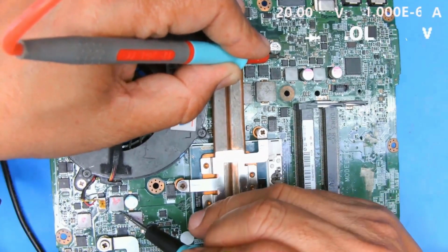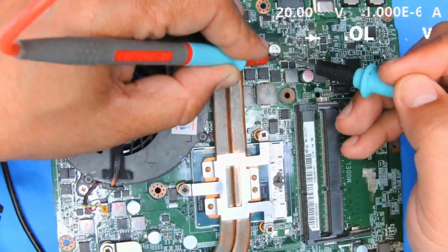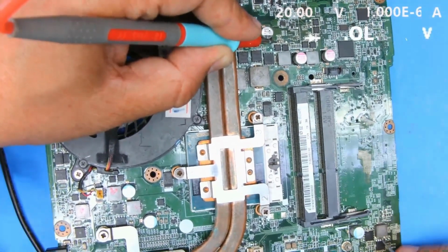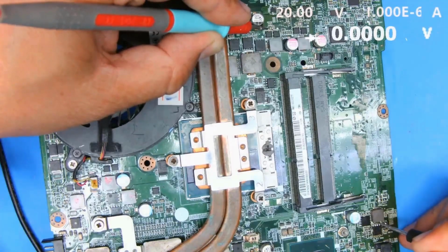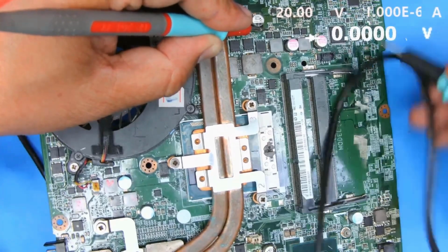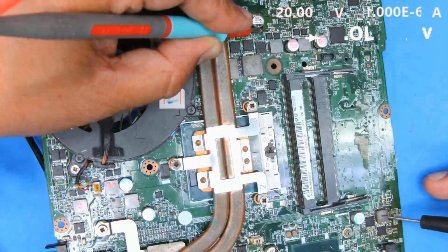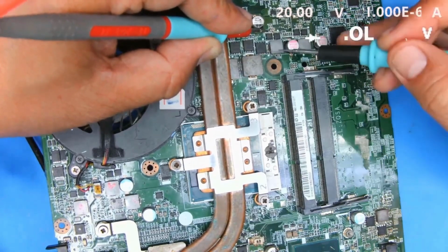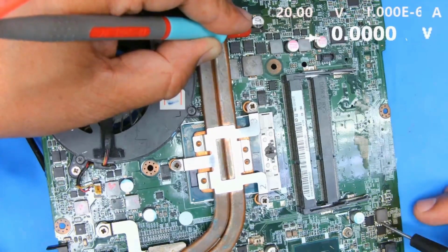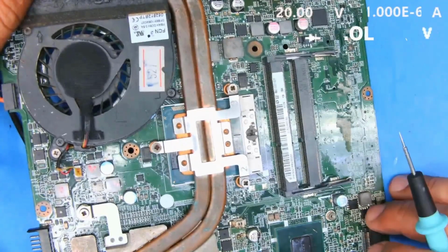This one isn't it. This one isn't it either. This one isn't it, see? We're only moving the black probe, we're not moving the red one. Pin 49 is already connected to everything, so we just keep moving and probing along. See, this one reads 0.000. This shows that this point on the positive side of pin 49 is connected here, like there's continuity between them. That means the drain and the source of the MOSFET high side here are shorted. It's shorted right here. Now we know that the MOSFET high side is shorted at this spot, and we didn't even have to power it on.